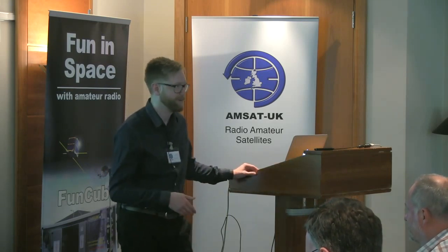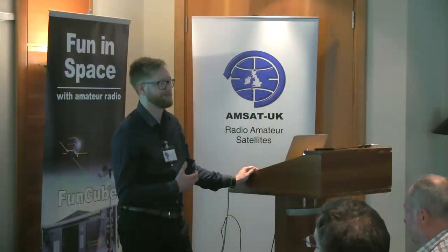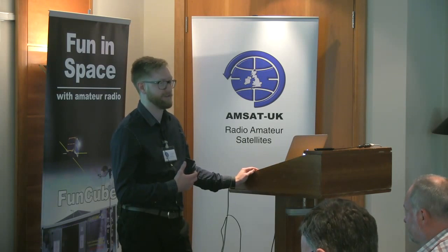I wouldn't say that you're buying back. So this is a definition of terms here where we're actually jumping to quite distinct boundaries. A processor gain would be a performance improvement of some respects. Now, if I measure that in dBs, that already means that I'm probably thinking slightly differently to what I would expect if I'm thinking about my iPhone processor or a Raspberry Pi processor. So with a processor, I'm thinking MIPS, clock cycles, amount of floating point operations that I can perform. Whereas if I'm thinking in dBs, I'm thinking, okay, what am I trading off here for a given link budget? I'm trading off data rates with gains and losses in my system.